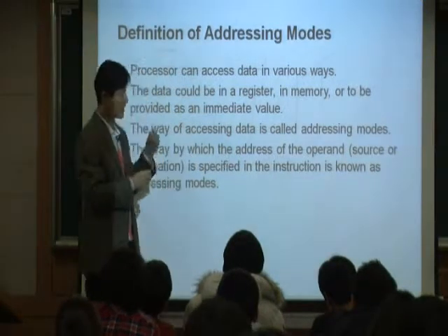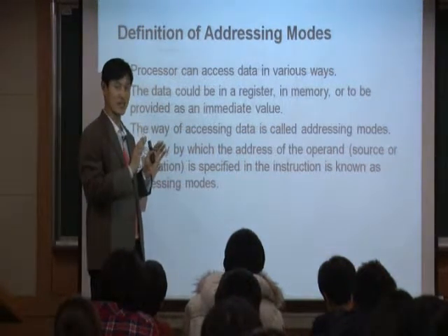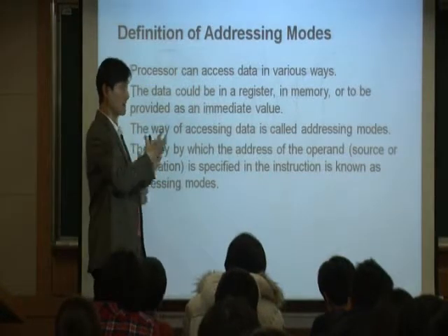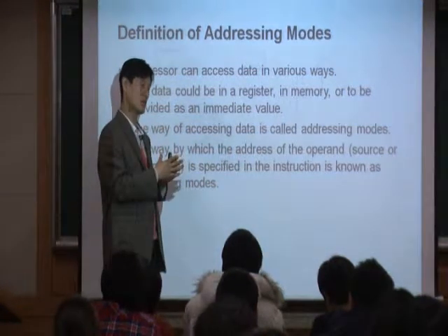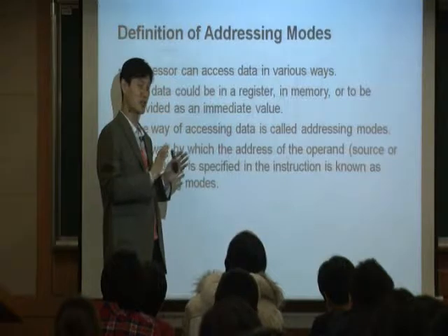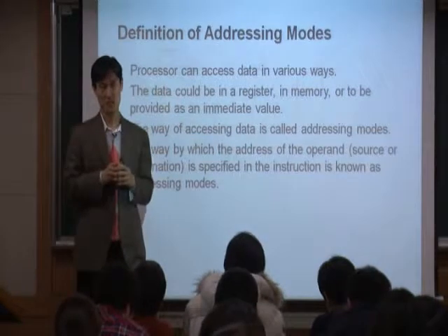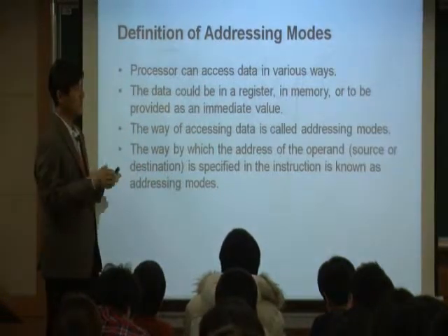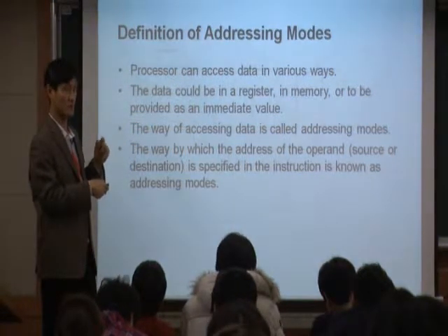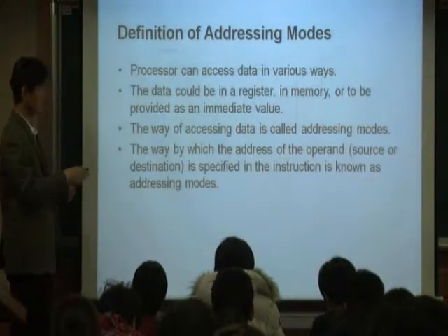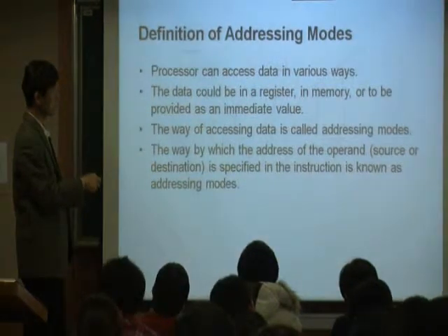But actually, if you learn these things, microprocessor, right? We are not covering any C language here in this course, right? We are only talking about microprocessor, memory, hardware, things like this. But once you understand this one, then now you understand the pointer. Pointer in C language is exactly the same as one of the addressing modes in assembly here. And that's actually indirect mode, indirect addressing mode. So let's look at one by one. There are 5 different addressing modes in 8051. Okay? First one,